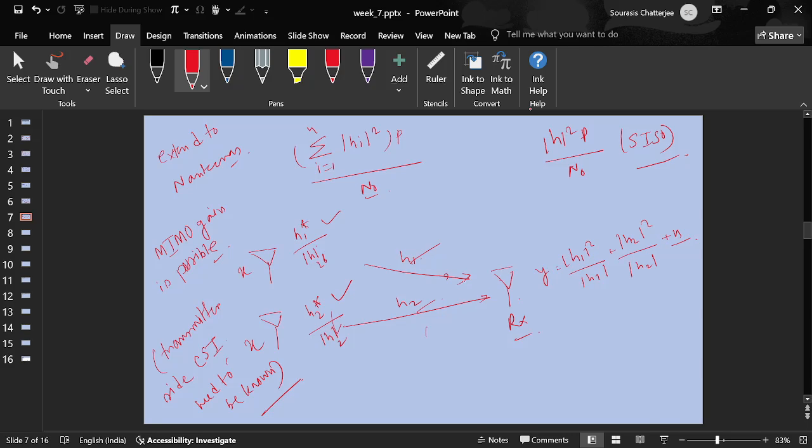So in that scenario, your uplink is happening at a different frequency band. So whatever channel information you obtained here, you cannot use the same as the precoding weight here, because your downlink channel is from some other frequency band, and these H1 star and these H1 are not going to match. So if you work in FDD mode, that is frequency division duplex, this will fail because the reciprocity won't hold. Your downlink and uplink channels are not the same.